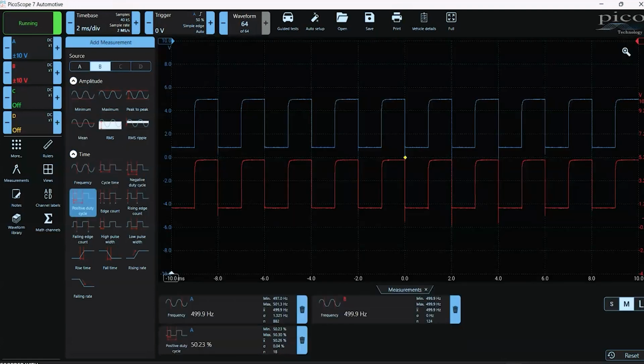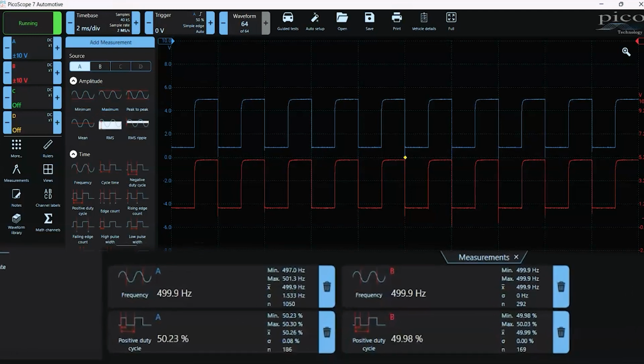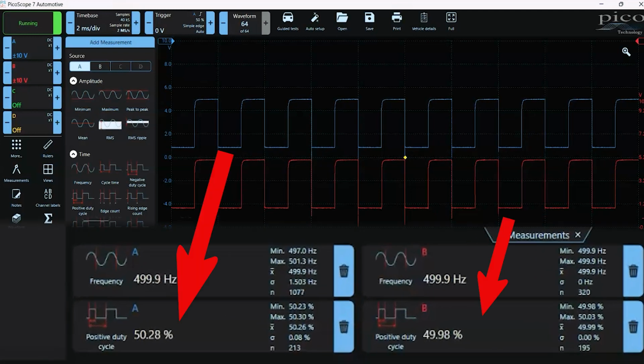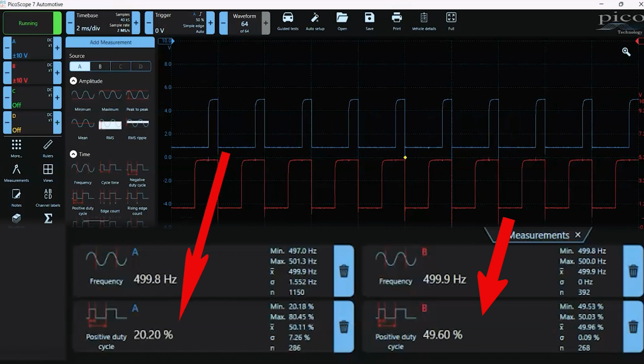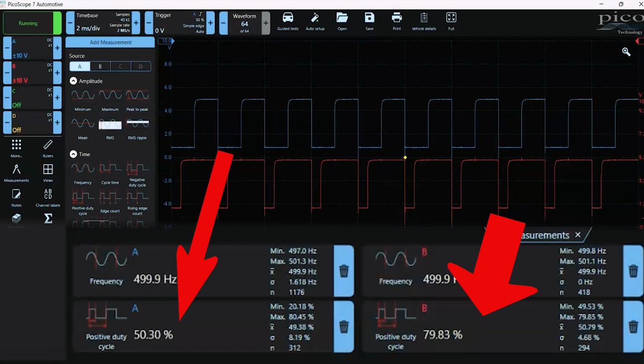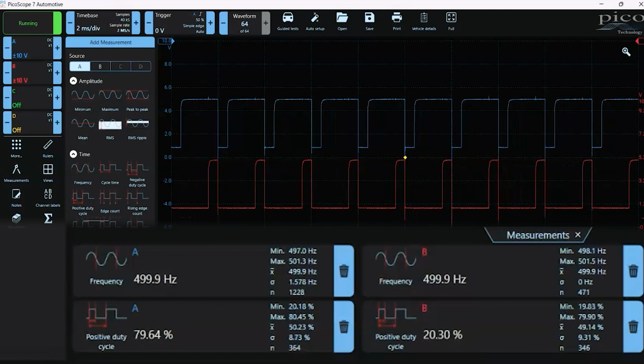It is important to replicate this precisely because the computer will give you error codes if it sees something is off from the signals. It is a 5-volt signal at 500 Hz, and it varies from 80% to 20% duty cycle. Luckily enough, the Arduino Uno we're using also spits out a 5-volt signal at 500 Hz.